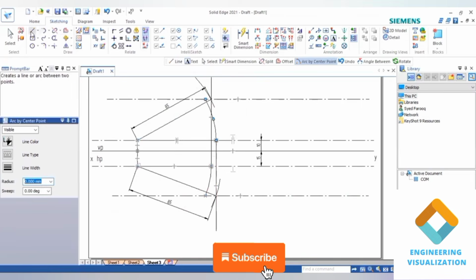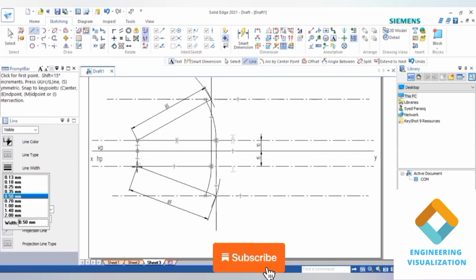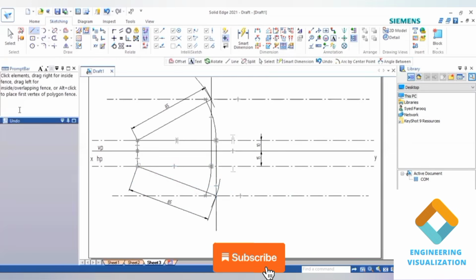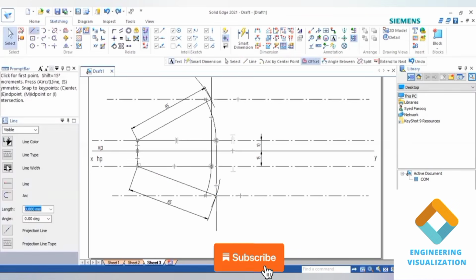Okay, now go to line and select thick line, 0.50 mm thickness. So apparent length you always show with the thick line.